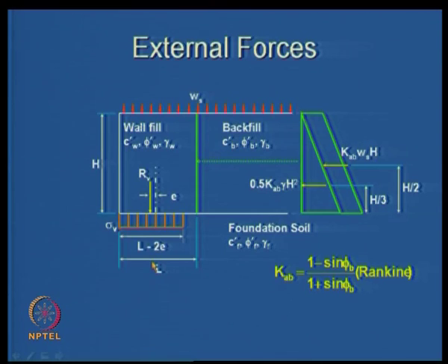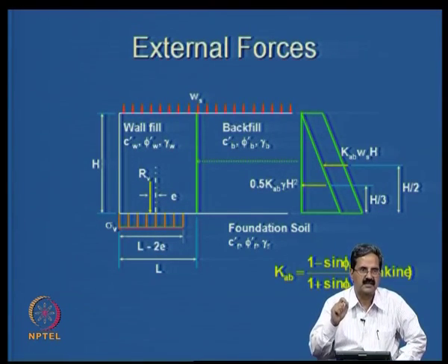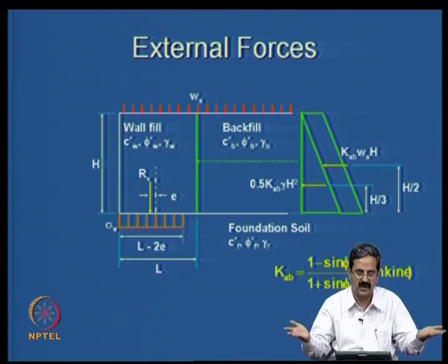You know that we have a trapezoidal distribution, where you have a maximum pressure developed and then a minimum pressure developed, and we have that B by 6 rule, right? That B by 6 rule is very important, and here also we measure a similar thing, and that is called trapezoidal distribution. That is valid for stiff footings, I mean rigid footings like concrete footings and all that.